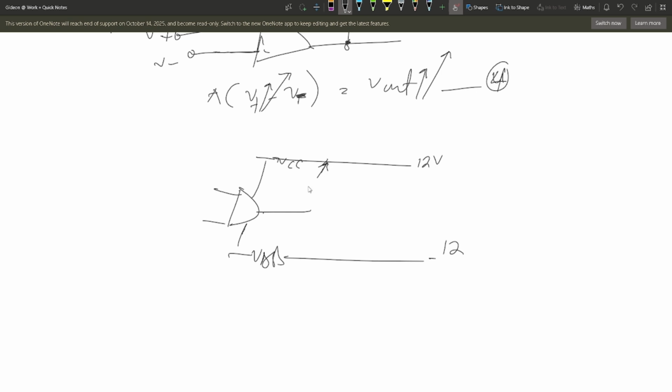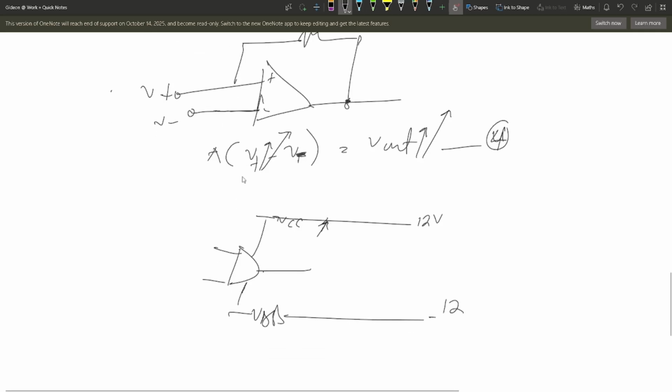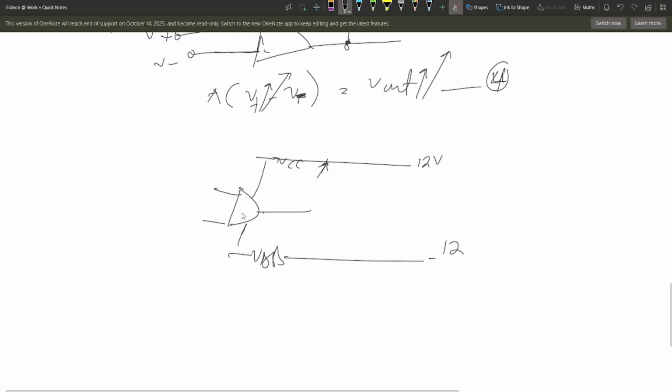Normally, positive feedback circuits are used in oscillation, to design oscillators. In this video, we are not going to talk about oscillators. We'll talk about oscillators in future videos. So I won't talk about this a lot, but I think you might appreciate the fact that with positive feedback, the circuit is driven to the highest voltage, or to saturation. So in a fraction of a second, the circuit gets to 12 volts in the positive feedback. Alright.